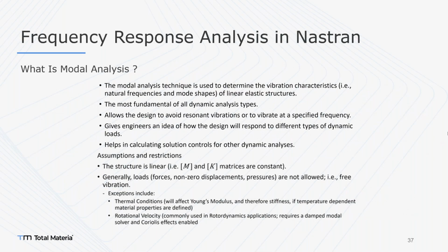So go on, please, Bartek. Yeah, before the frequency response analysis, I think what we need to define is modal analysis. Modal analysis gives us an understanding of the vibration characteristics of a system or a component. It is the first step for dynamic analysis, and the most basic.